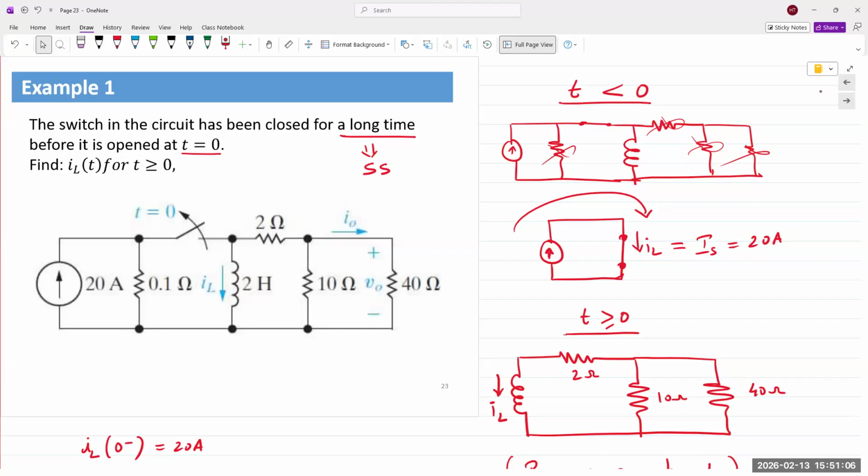It would barely lose 0.1 volt. So it's fully charged to 10, it might drop to about 9.9, and the next positive cycle arrives and it starts charging again. So it's a continuous cycle of charge, discharge, charge, discharge, and it only falls less than 100 millivolts, 0.1 volt, or even smaller than that if you want a full flat DC line.